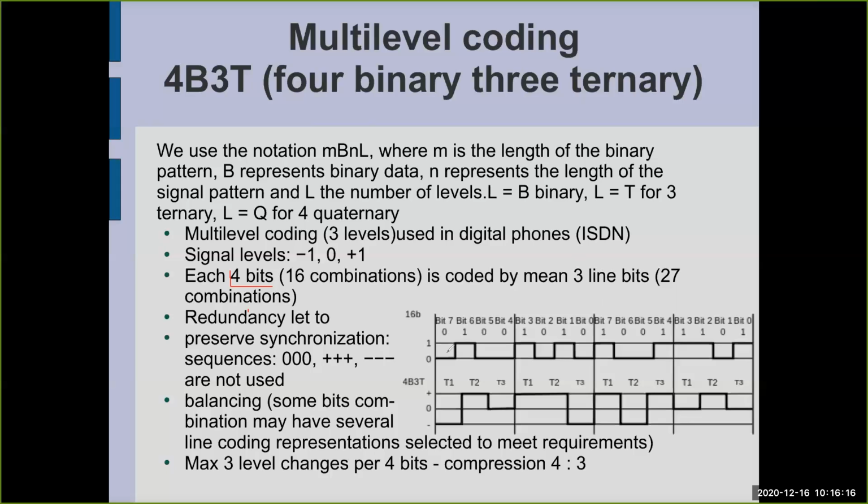Look, here I have data bits. This is the first group. In line coding, this value is converted to a signal which looks like this. The signal changes from -V, then +V, then 0. This group is coded differently.